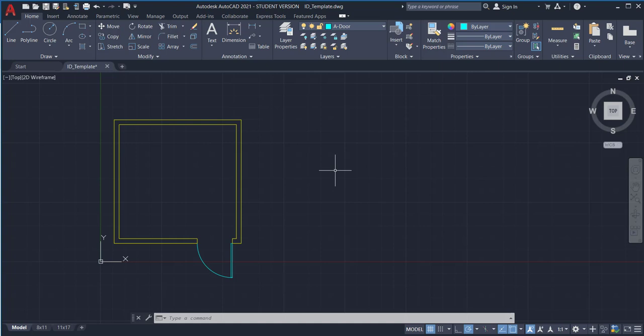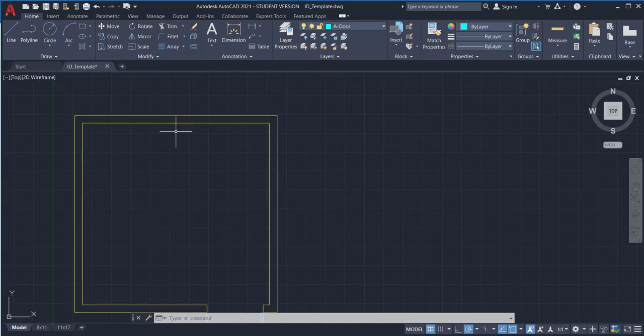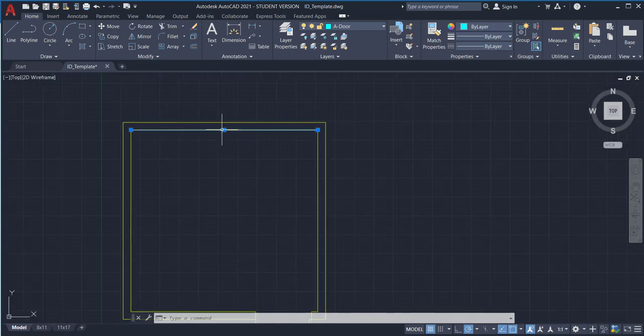So now that we have the door installed, let's add a window, and this works very much the same way as the door. Now I don't have a smart window to give you, so that means that we're going to be drawing all of our windows. What we're going to do is center a 3-foot window on this back wall over here, so kind of the opposite side of where this door is. The first thing I want to do is know where the center of this is. And I always go with the interior wall and mark the center from there.